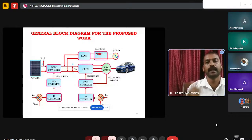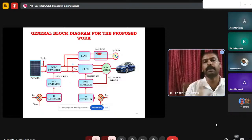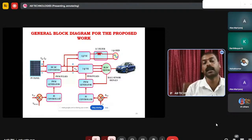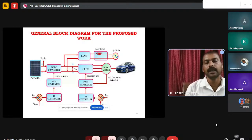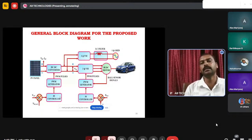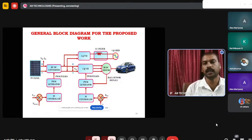That reference power and the actual power we are comparing. That error is given to the particular MPPT algorithm, which may be P and O, incremental conductance, fuzzy logic algorithms, or neural network, or any other intelligent controller you can take. That controller converts the high value of power error into less than 1. Why? Because the amplitude of the carrier signal is 1 volt.